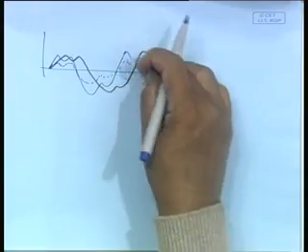Remember that period is length, therefore height and period essentially implies also the slope of the graph. Height and length means H by lambda, which means the slope, the steepness of the wave. So I need a description of ocean waves which also gives me the steepness. Now this is what we will be talking about later, how we can generate this.